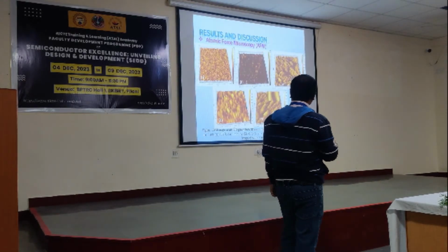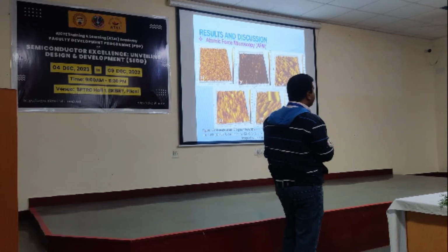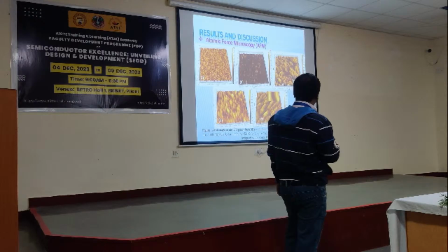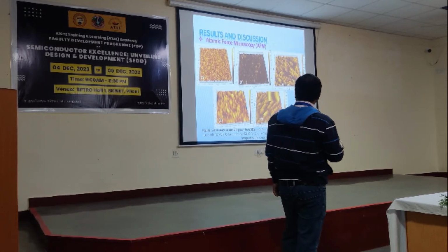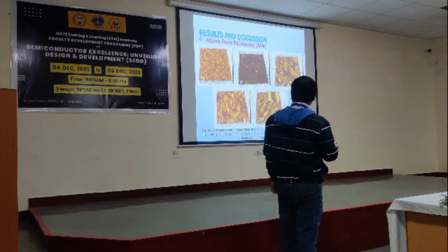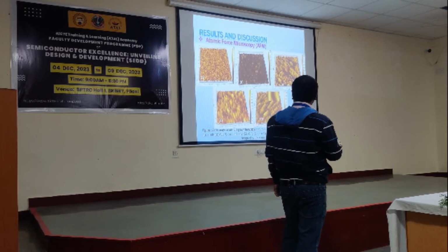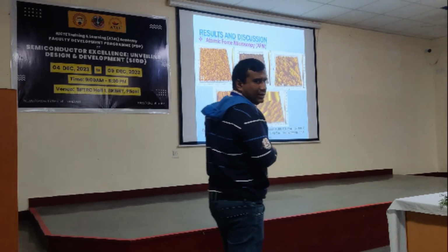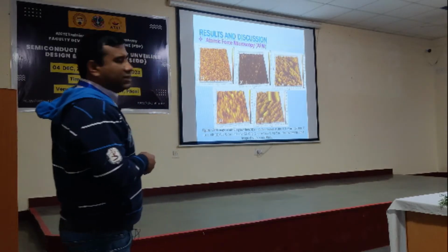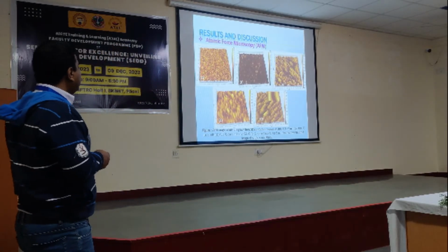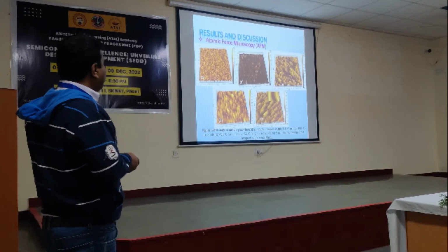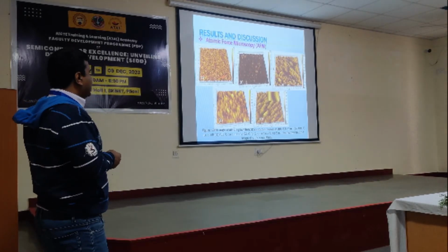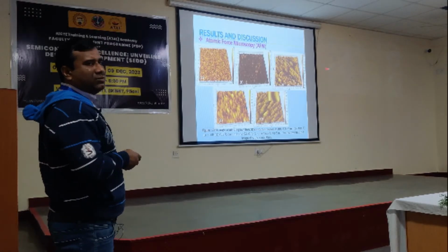Now you see these are the AFM images. AFM is atomic force microscopy. These are atomic force microscopy images of the indium arsenide quantum dot on gallium arsenide substrate. This one is 380°, this is 400°, this is 450°, and the last one is 530° centigrade. You can see that when the temperature increases from 380° centigrade to 530° centigrade, the size of the quantum dot increases.